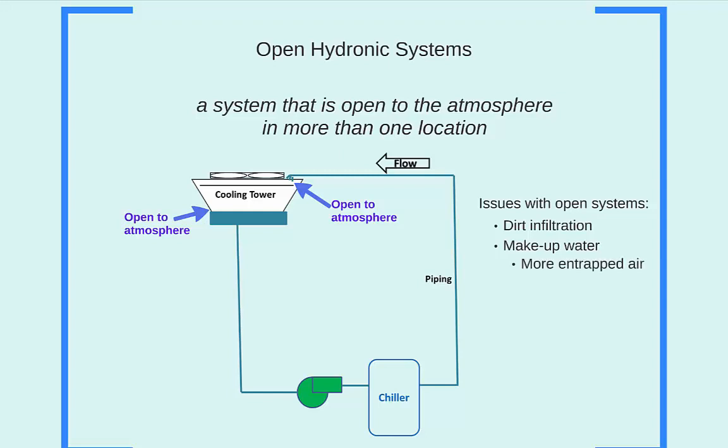An additional issue that arises is the system now operates at higher concentrations of calcium and other minerals that are not evaporated when the water evaporates in the cooling tower. The last issue with open systems is there is an increased risk of cavitation if the design engineer doesn't understand the added precautions that need to take place for open systems. Further discussion on that is beyond the scope of this course, but it is discussed in the HVAC design and analysis courses taught here at AFIT.